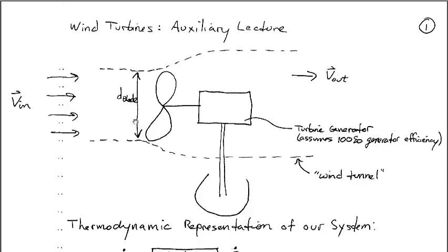I'm just giving you the two-dimensional representation here. We have a dimension in the y direction and we have a dimension in the x direction with the flow of the wind. Now if you position yourself right here and look into the center line of this blade, or the center line of this rotating shaft, you'll realize that these rotating blades are in fact sweeping out an area. And the diameter of that area is, of course, the diameter of the blades. So this blade diameter is essentially the characteristic measurement of what is called the effective flow area.